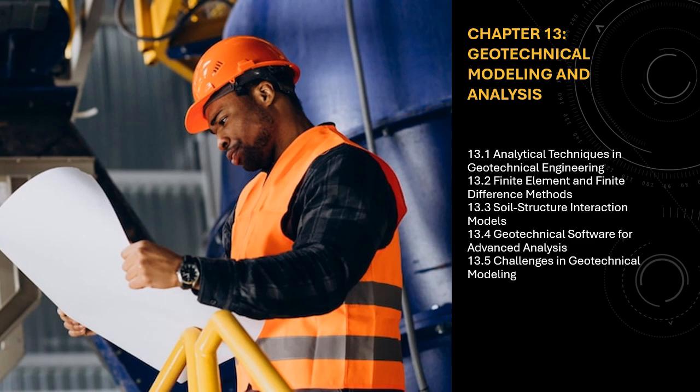13.2.2.3 Advantages of FDM in geotechnical engineering. Simplicity. FDM is conceptually simpler than FEM and is relatively easy to implement, particularly for problems involving simple geometries or uniform grids. Efficiency. For problems with a regular, structured grid, FDM is often computationally more efficient than FEM, especially when modeling large domains or when dealing with time-dependent processes.